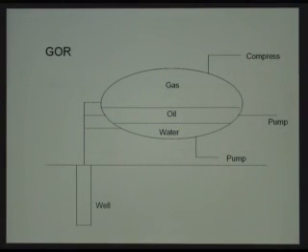Now, I don't know if they covered this in the process section that you've been through, but out of the wells from the formation, you get not only oil, but you get gas and water. And those go into a big vessel called a separator, where they separate out into their constituent parts. And the water gets put back into the ground, the oil gets pumped for further processing, and the gas you need to compress, a little bit goes for fuel, and the rest of it goes back down into the ground.